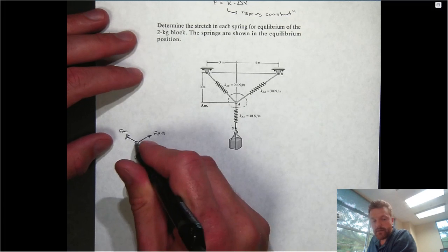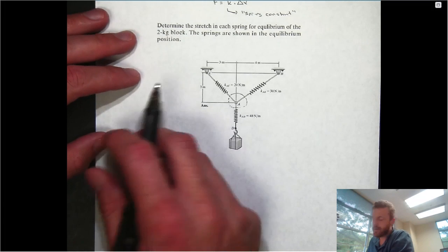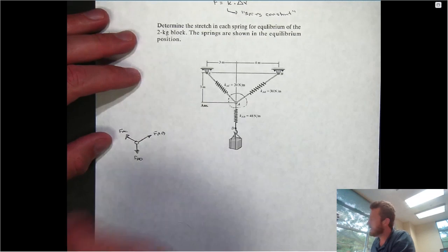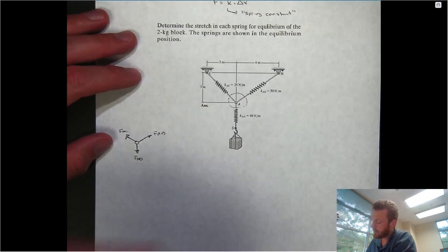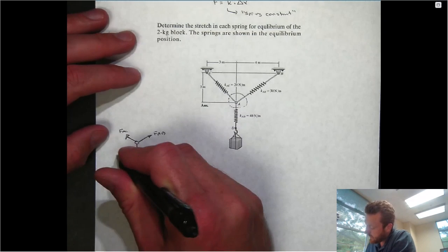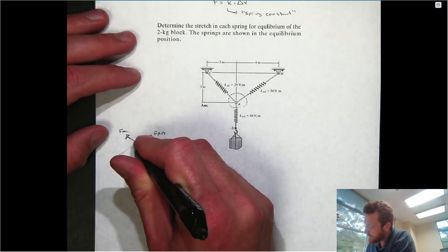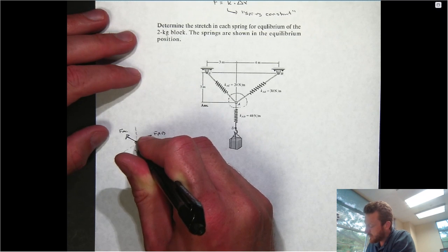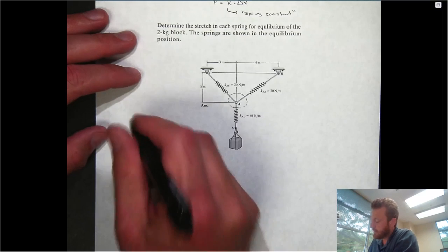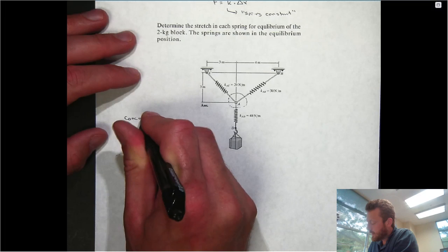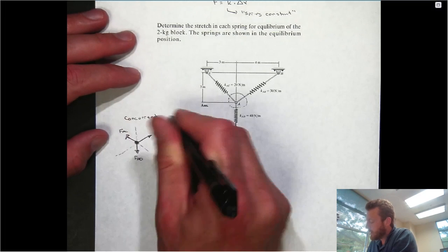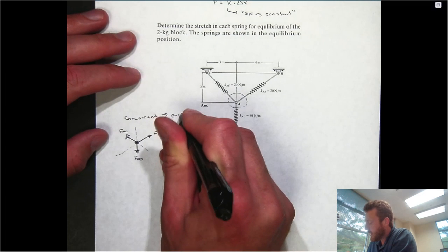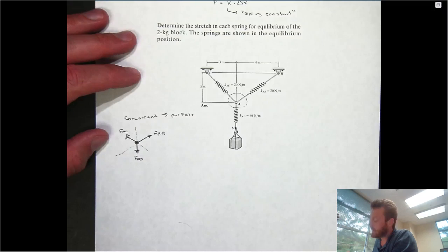Now, naturally, this O-ring has some dimensions to it, right? It's a fabricated real structure. So it might not be immediately obvious that we can model this as a particle. However, if we extend the lines of action of each of these forces, we'll note that all of their lines of action pass through a point which is dead in the center of that O-ring. So we called those concurrent forces. And we said whenever forces were concurrent, that a particle model was a valid form of analysis.